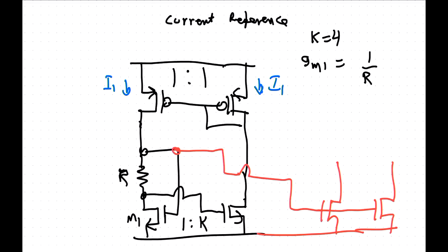This might actually be the natural state that it boots up in. Because, as I said, what you probably do is to have a lot of transistors that hang on this node here to bias all the current sources. It means that you have a very large capacitance to ground on this node. You might also use these PMOS devices to bias your PMOS devices, which means that you have a very large capacitance to VDD on that node.